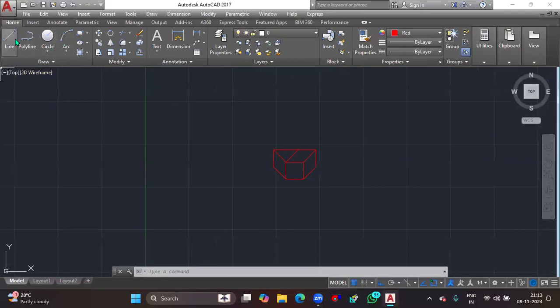Now let's talk about the line with the angle command. I hope it is clear. For that angle, you can either use the less than symbol and enter the command, or you can use the tab command. But the better method is using the less than symbol. Why? Because you can actually enter the length value also. All right, that is the concept behind it.